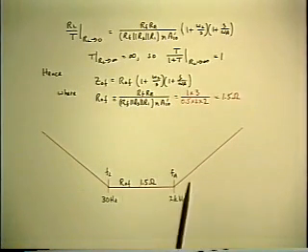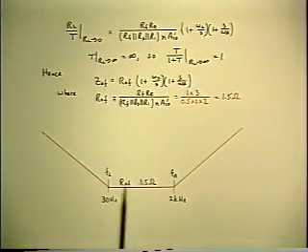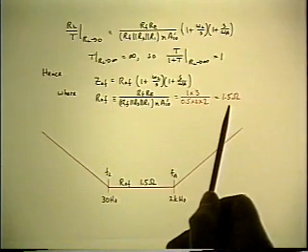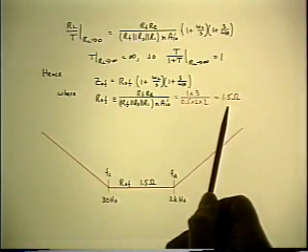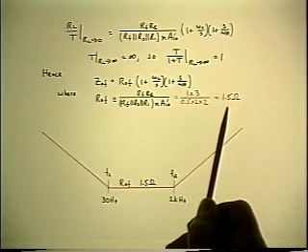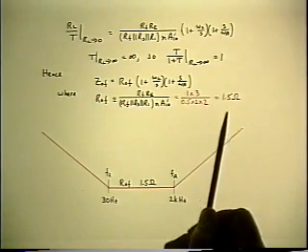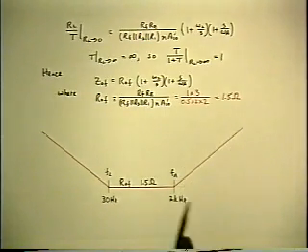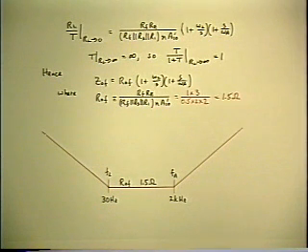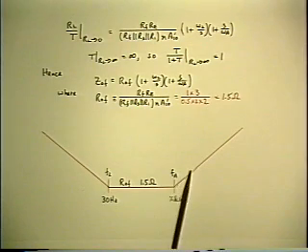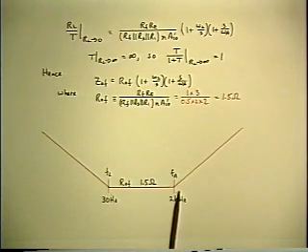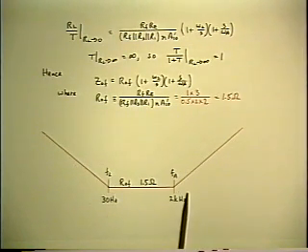Okay. Relate this to what you expect. The mid-band output resistance is very small. It's 1/10 of the load resistance, as a result of the fact that inside and outside output impedances both will be much lower than the load itself. However, it's only low over a relatively narrow frequency range.